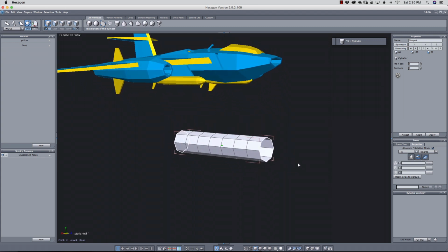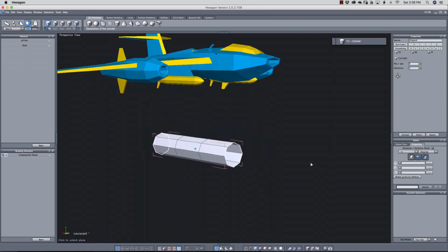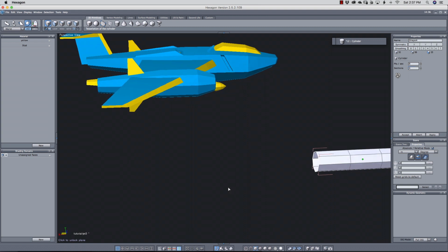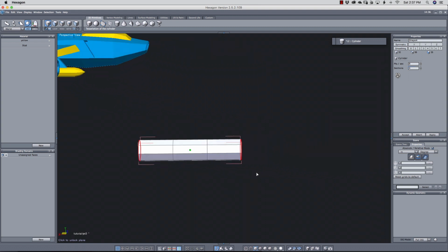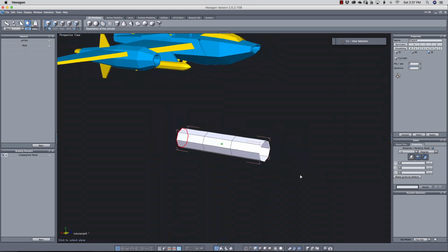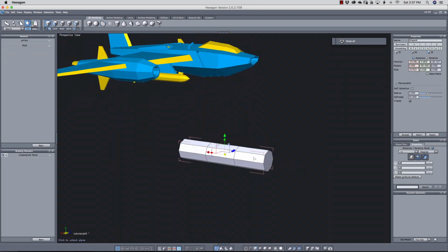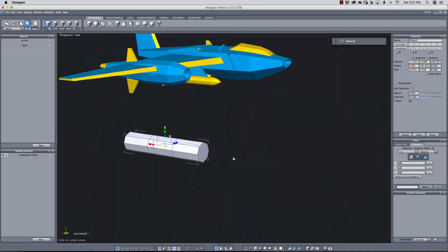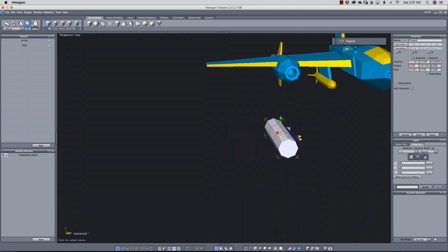Okay, if we look here, it's splitting into 8 sections. I want to lower that to just 4. And before I confirm, I'll hover over these openings and click on them, and that closes the holes. I can press again to reopen one, but additionally, this button here closes all the openings. However, if I click on that, it accepts the shape, and then all of my options disappear. That's what I wanted in this case, so we're fine. I'll move it here so we can see it better.